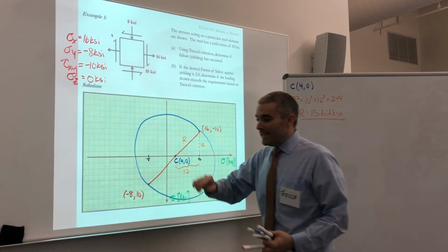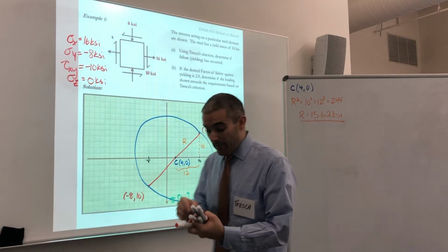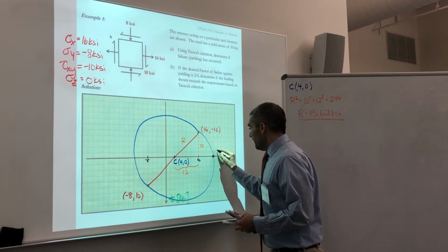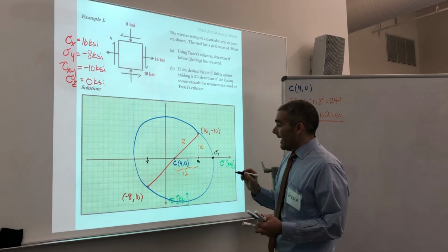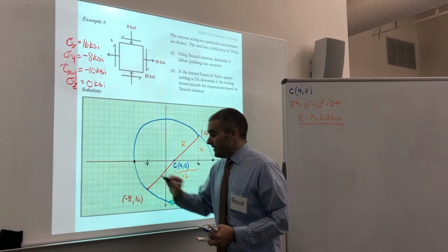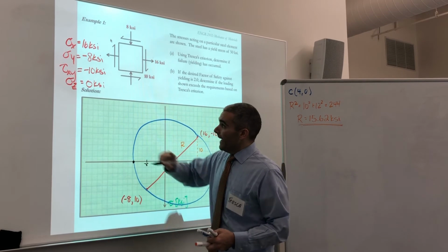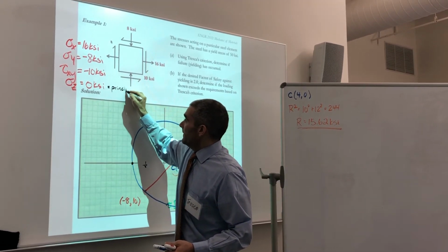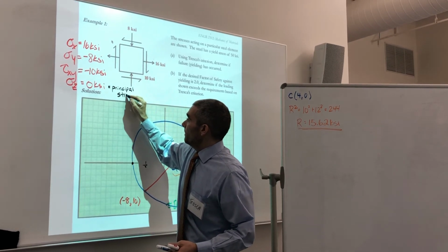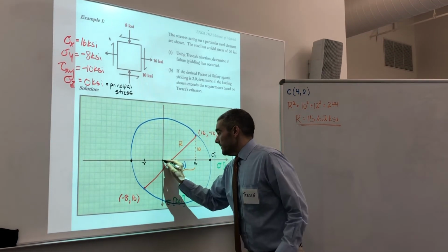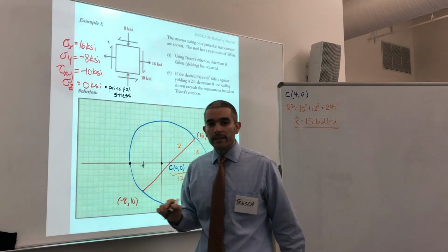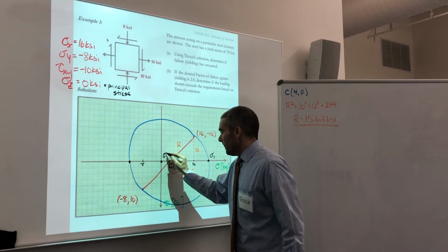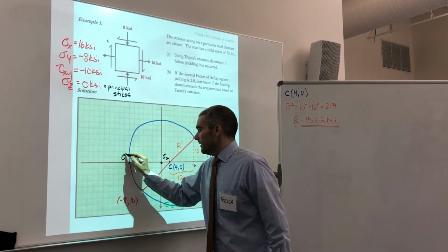All right, I'd like to be complete, so let's go ahead and identify some of our principal stresses. This would be our first principal stress. We have another principal stress over here, and then don't forget that sigma z is also a principal stress. So I also have to have a principal stress here at 0. Then I'll just algebraically number them sigma 1, sigma 2, sigma 3.